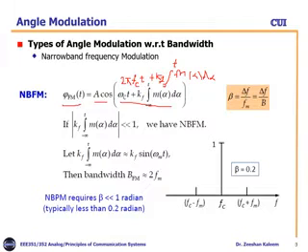For a signal to be narrowband, there is a condition that the amplitude of this part, kf into the message signal, should be less than 1. This is the important condition. If this is very much less than 1, then we can name it a narrowband FM, or we will have a narrowband FM signal. As its name suggests, narrowband means that it will consume less bandwidth, less amount of bandwidth, BW.